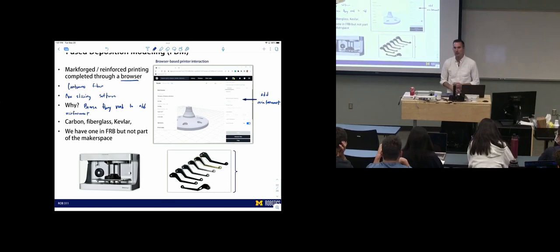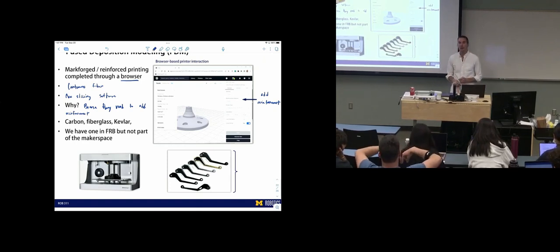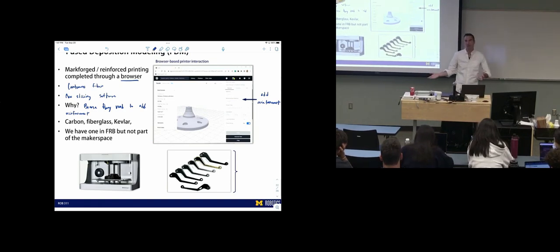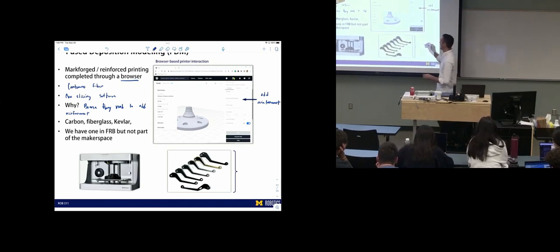So the approach to printing is still the same, but I thought you said there's no slicing, so it's just coming out at the same time? It's coming through a separate process, but yes, in parallel. Oh, okay. So there's another spool with the fiber on it. You don't have to use the fiber when you don't need it. It just makes it stronger, and you can isolate it. For example, if this were a handle, right here would be an excellent place to support.